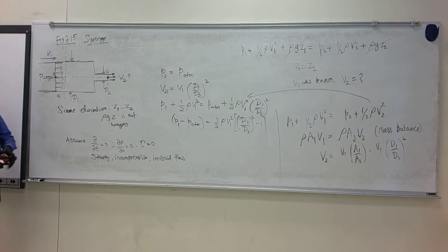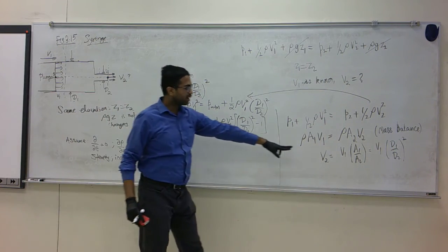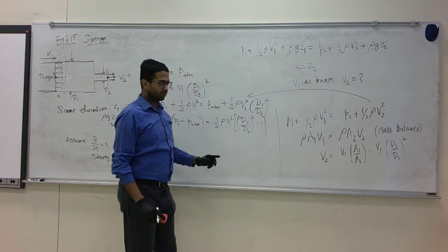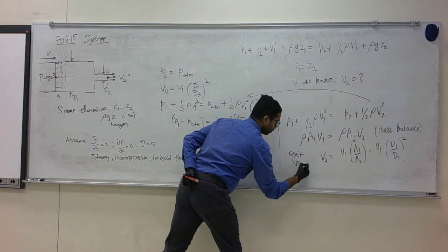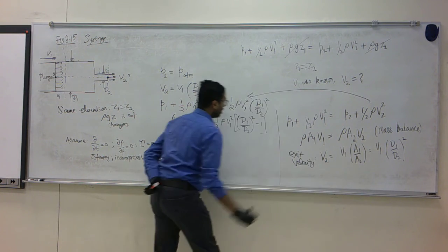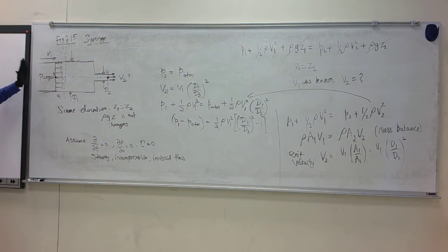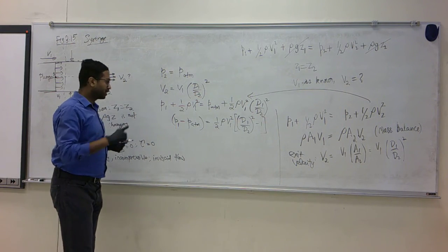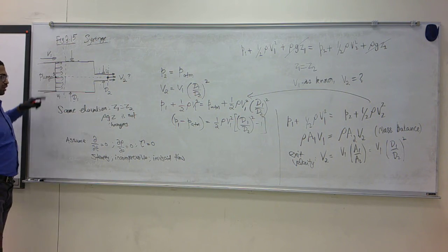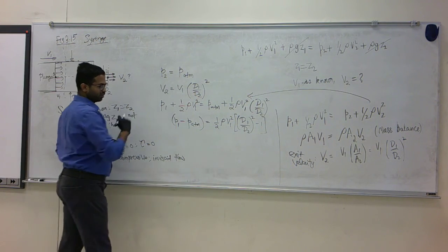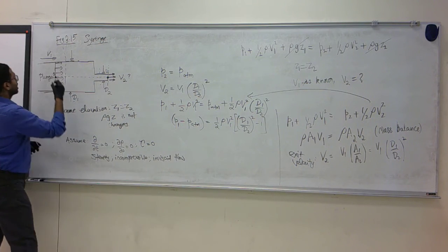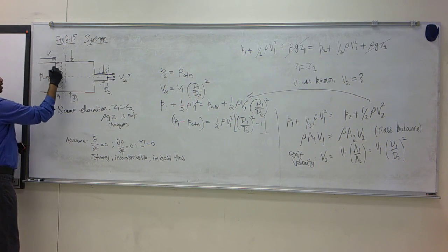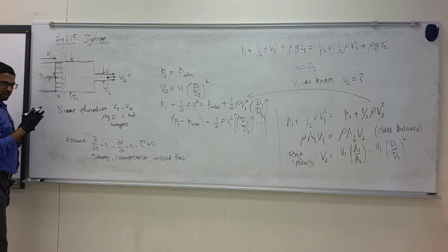Okay. With this equation and the area ratio, you can get V2, that is the exit velocity. V1, the plunger velocity, is something that you can control because you press it with your finger. And since it is discharging to the atmosphere, you can figure out the pressure at the surface where the plunger and the fluid are in contact.